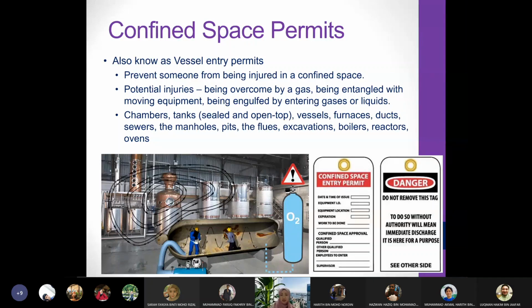One of them is you can become overcome by a gas. Suddenly there's a volatile fluid in there. You can become entangled with moving equipment, and in a confined space it's really hard to move, or you can be engulfed by any gases or liquids that enter.